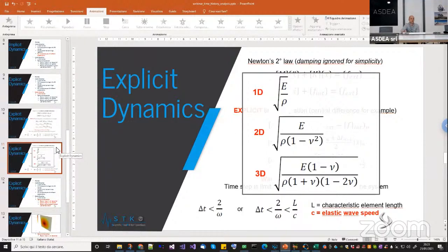Was the earthquake applied at the bottom support constraint of the piers? Yes, because I used the uniform excitation. Whenever you use the uniform excitation, it will be applied to every fixed node, or every node that is fixed in that degree of freedom. If instead you want to selectively apply a ground motion only at certain locations, then you have to use the ground motion command, not the uniform excitation.